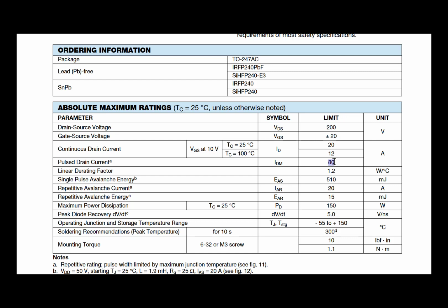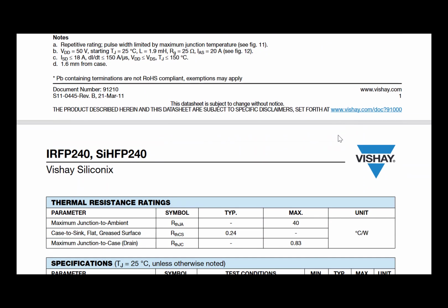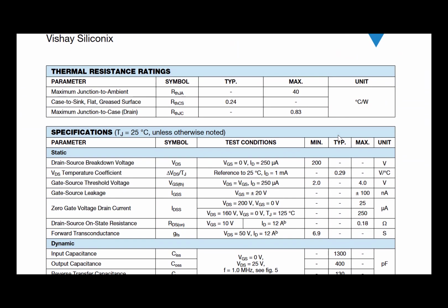Now, in our specific case, we will be running simulations, but we will try our best not to exceed these values. So you will see for my simulations, I will try to stop with the VDS at values around 10 volt, so we make sure we are conservative, and also with the gate source voltage at values which are around 10 volt. Obviously, in a real-life circuit, of course, you would need to take into account safe operating conditions in a much more serious way.